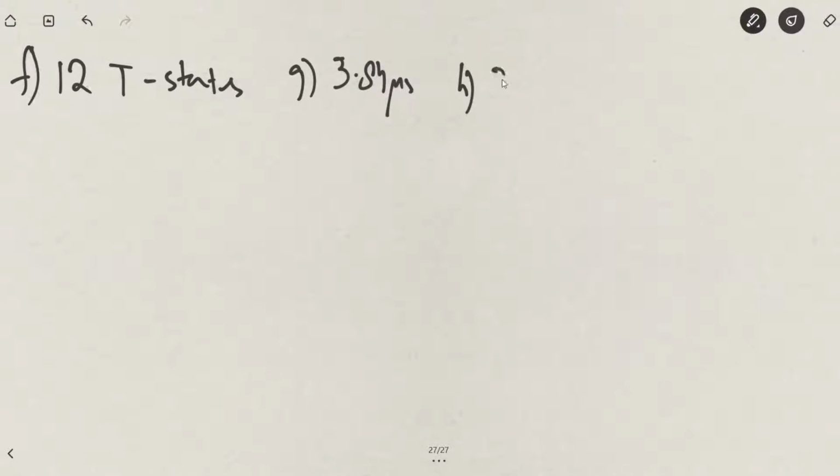The last instruction that we studied was RSTN, which was also related to the stack pointer. So wherever you have stack pointer based instructions, all of them will have a 6 T state opcode fetch machine cycle. So 6 T states of the opcode fetch, plus 3 T states each for the memory write machine cycles, makes it 12 T states, and therefore an execution time of 3.84 microseconds, with 3 variations.